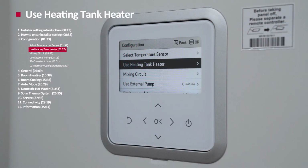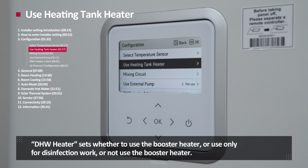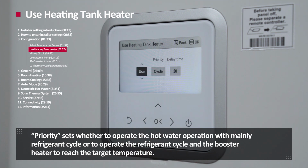Use heating tank heater. Use heating tank heater setting is to determine how to utilize the booster heater for hot water operation. The HW heater sets whether to use the booster heater, or use only for disinfection work, or not use the booster heater. Priority sets whether to operate the hot water operation with mainly refrigerant cycle, or to operate the refrigerant cycle and the booster heater to reach the target temperature.